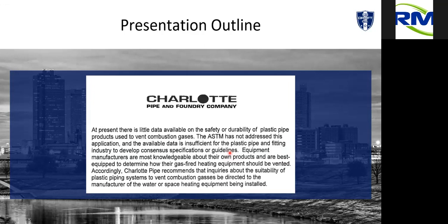Now, there is one manufacturer that I've heard of that is tested for very specific applications using a very specific PVC that has been tested to that, but honestly, there are so few and far between applications that it qualifies for. I typically don't bring that up, but again, you can use a polypropylene, you can use various grades of stainless steel, and typically the reason why PVC is used is for cost. Once you get above about 6 inch in diameter, the cost of PVC is actually higher than some of the UL rated products anyway. So kind of takes that out.